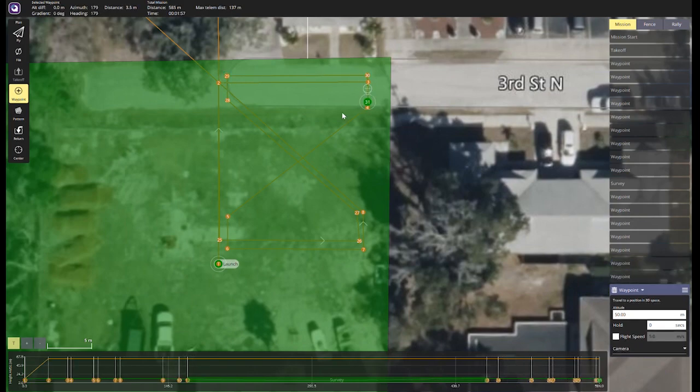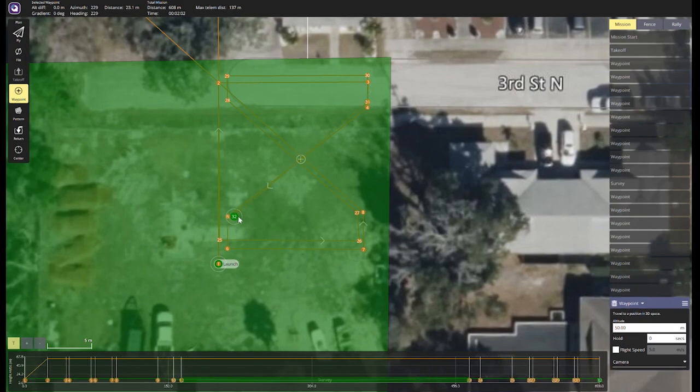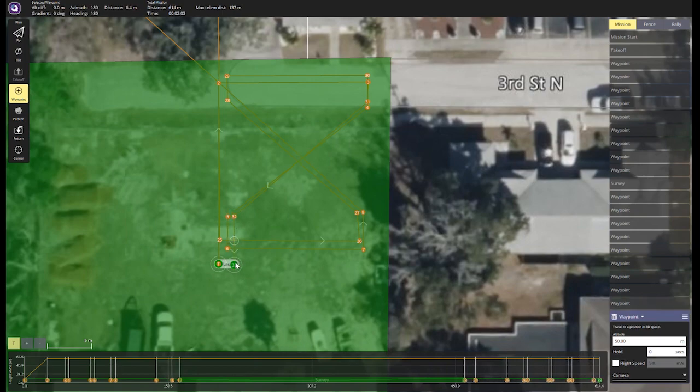After the finalization of the figure 8, create a clean path close to your initial takeoff point. If there isn't a return to launch function already set, create a final waypoint and select the white drop-down arrow to change the function from waypoint to return to launch.